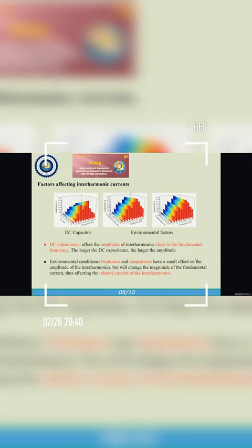When the DC voltage is output from the MPPT, the MPPT exhibits the characteristics of 3-point oscillation with angular frequency near the maximum power point. System parameters such as DC capacitance likewise affect interharmonics.